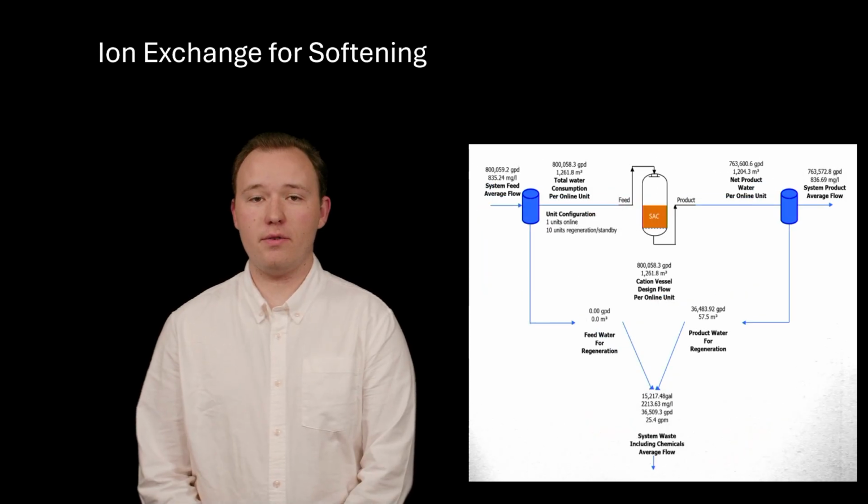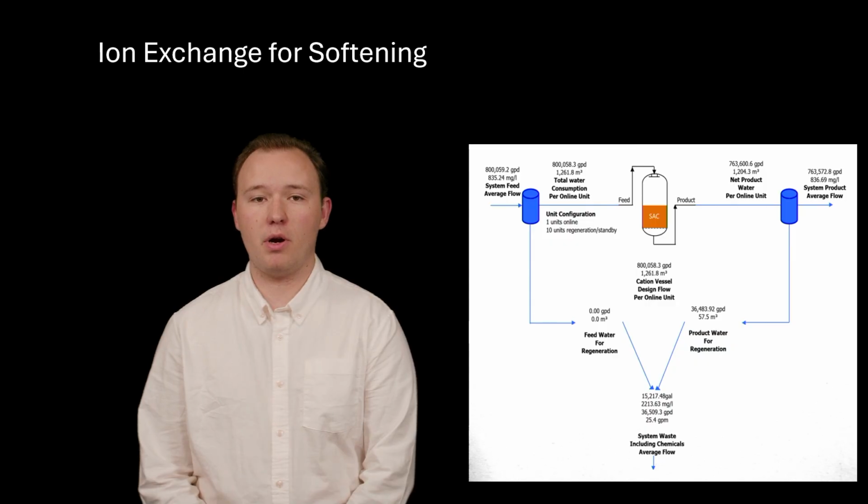Two of the biggest driving factors in our water-saving quantifications are the total dissolved solids and total hardness present in the water being fed into the tower. Ion exchange is an exceptionally capable process for the removal of these solids, and in particular dissolved salts and chlorides. The ion exchange process is capable of targeting both positively charged cations and negatively charged anions present in water supplies, allowing for the mass removal of our most targeted materials.